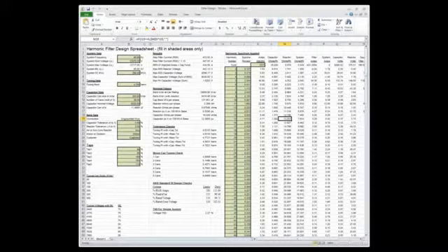So have any of you seen filter capacitor banks where there's several stages, maybe hooked in a binary configuration, where you can throw some on and take some off so that you're matching power factor more closely? In those conditions, I have seen times where for those type of arrangements there's vacuum bottle failures, and I think I've seen it mostly for just plain capacitors being applied on a bus.